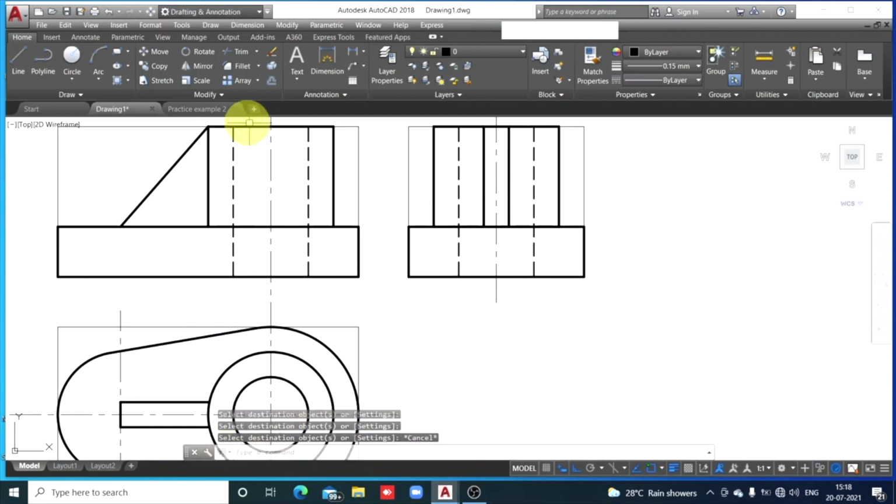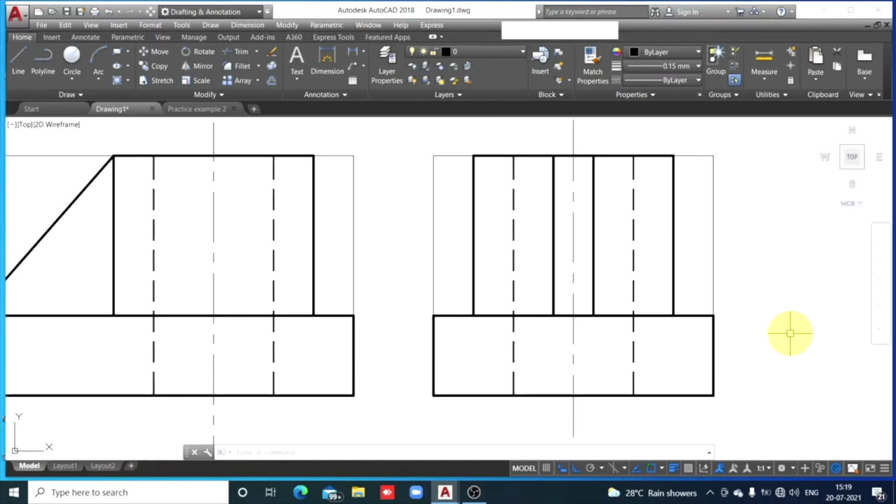Okay, now if I ask you where is this cylinder in the side view, show me this rectangle. And where is this triangular plate in the side view, show me this rectangular strip. What I am explaining to you, listen. The side view of the cylinder is this rectangle, and the side view of this triangular plate is this rectangular strip. Okay. The side views of these two parts, cylinder and triangular plate, overlap. So when this happens, you check for hidden details.